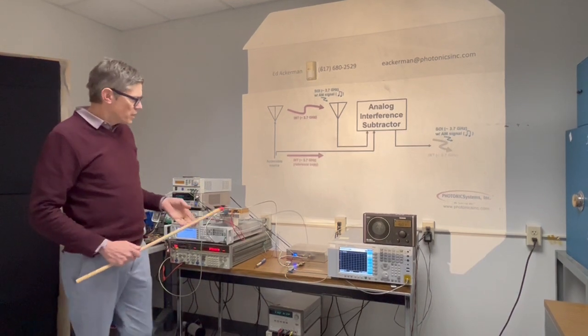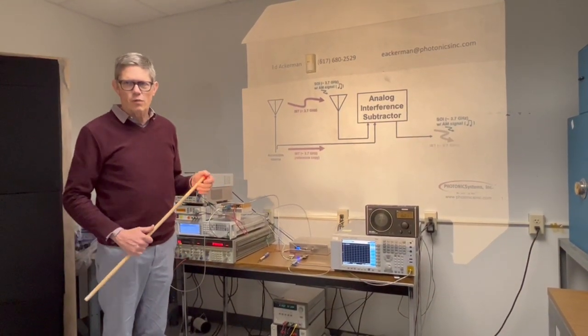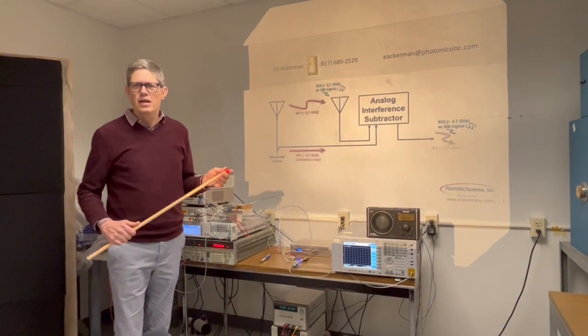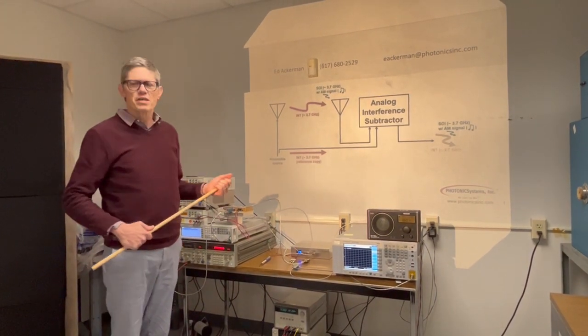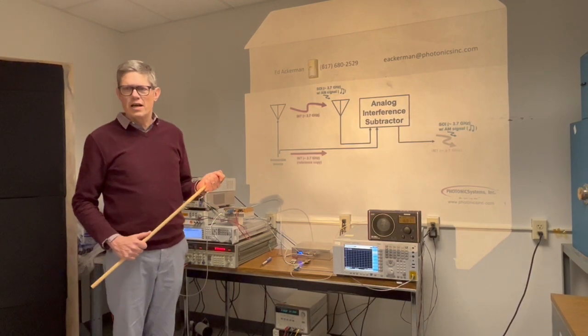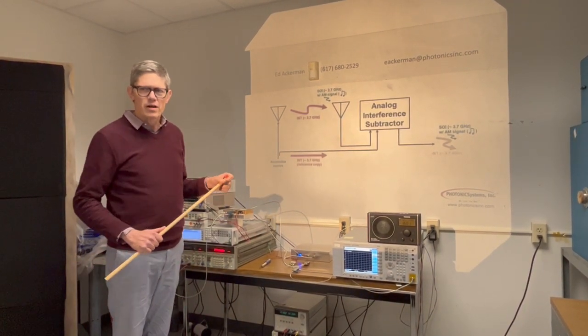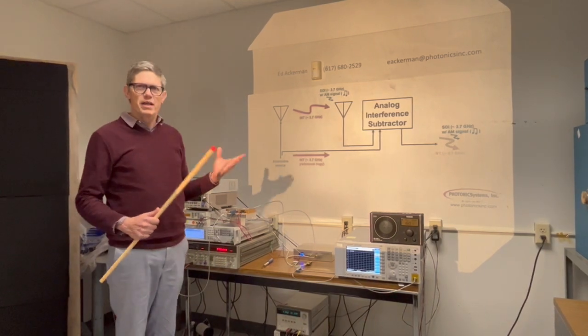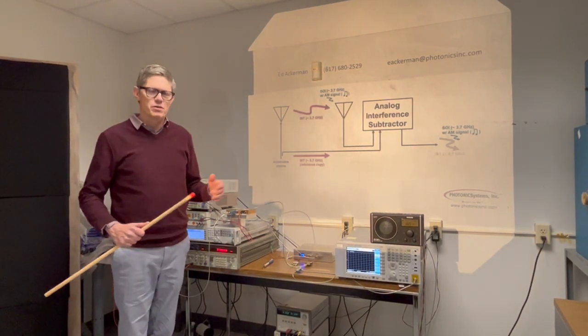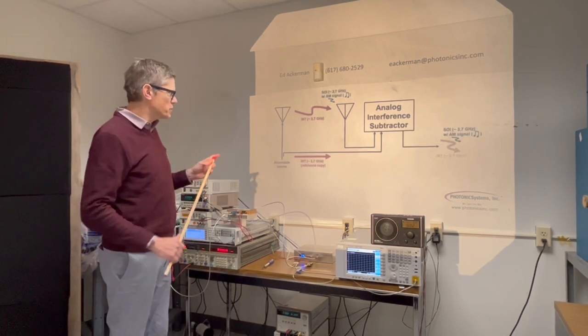Now the purpose of the interference eliminator is to address a very difficult situation where you have a signal of interest that you're trying to receive from some distance away, while there's some other closer antenna transmitting a much stronger signal, which we call the interferer. So it's difficult, and it might be right in the band of our signal of interest, so it's going to block our ability to receive the signal of interest with good signal to noise ratio.